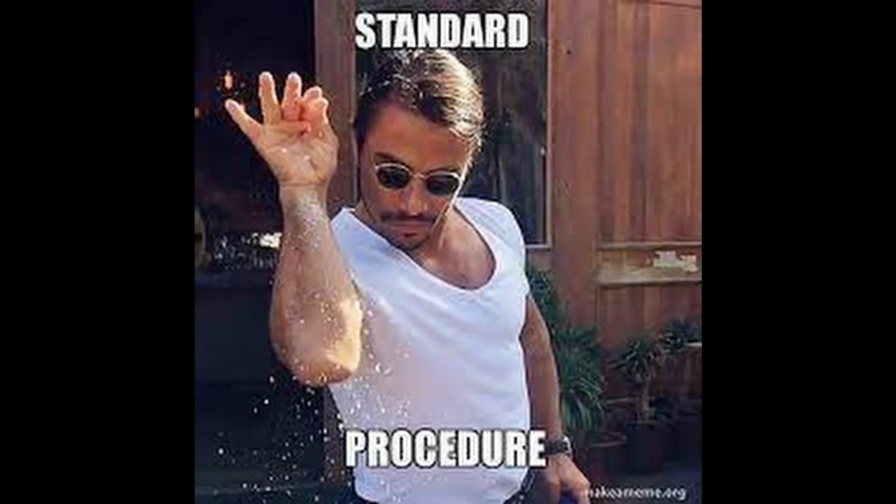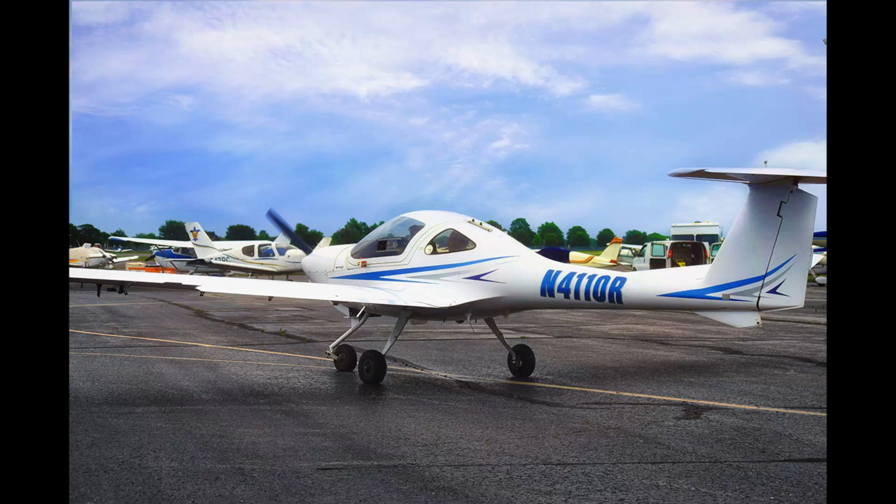A very common procedure taught to recover from a spin is the PAIR acronym: power idle, ailerons neutral, rudder full opposite, and elevator down briskly to break the stalled condition. Flight instructors are required to complete spin recovery training before getting their certificate.